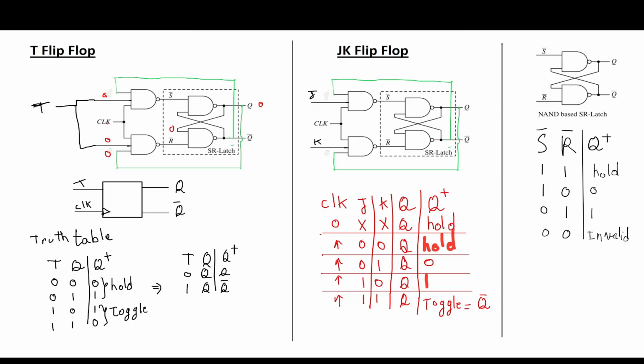And we want to assume we have edge trigger. So the clock will have edge trigger. So this is 1 here and 1 up here. So the bottom NAND gate, we have 1, 0, and 0. For 3-input NAND gate, if you look at the table, you only get 0 when all 3 inputs are 1s. So for 1, 0, 0, the output will be 1. So R bar will be 1.